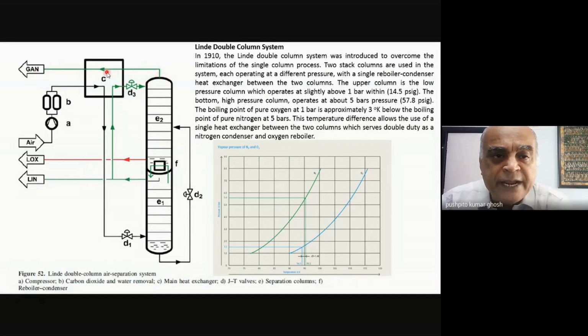Of course, when I take it through this heat exchanger, I do some heat exchange along with this stream before the expansion, and then again after the exit of the nitrogen from here, and all of those are cooling the incoming stream, and then later, finally, I'm doing a Joule-Thomson expansion. So this is what they were able to do to simultaneously get both very pure oxygen and very pure nitrogen.